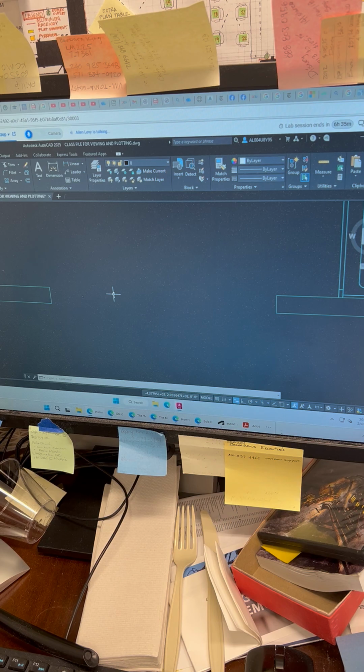All right, what I want everybody to do now is go ahead and turn that tool back on, the object snap. So come down to your status bar, click once on the little square with the little square in the upper left-hand corner of the square. With that turned on, try it again. Start the line command. Hover over the corner.